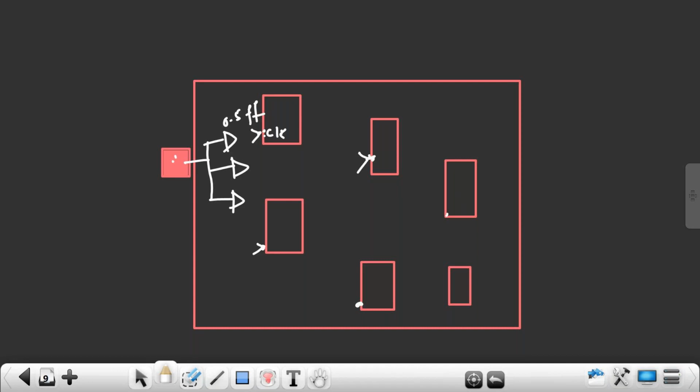Only 3 cells. So the 3 cells' pin capacitance will become load capacitance to what? This clock port. Now this load capacitance value is reduced. It is nothing but the sum of the 3 cells' pin capacitance. Now connect to this flip-flop. This buffer you connect here.